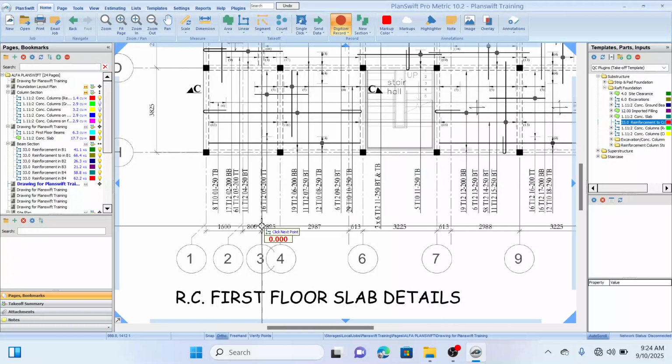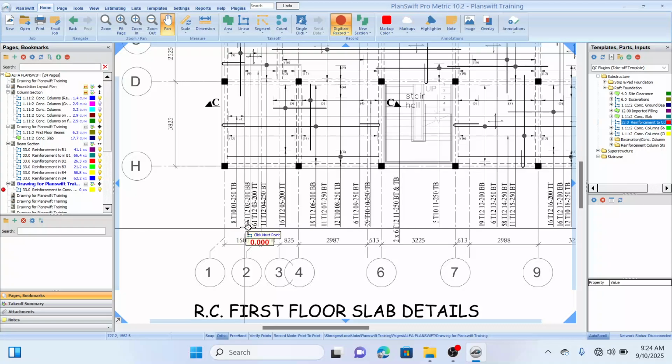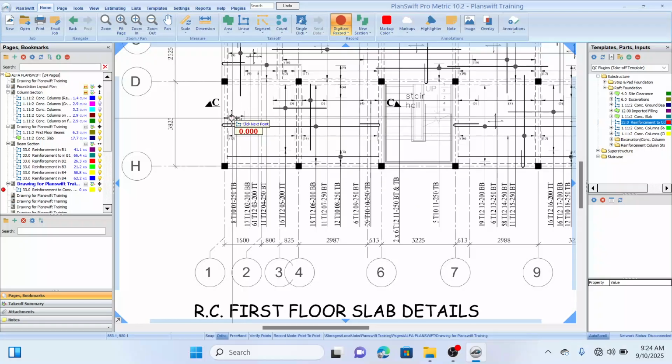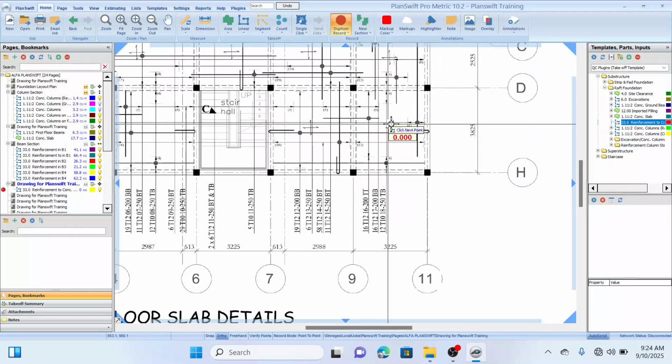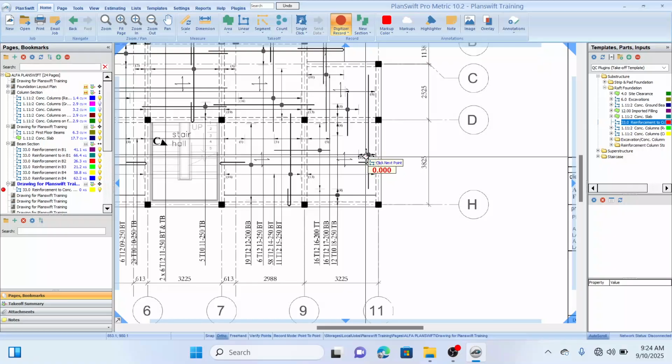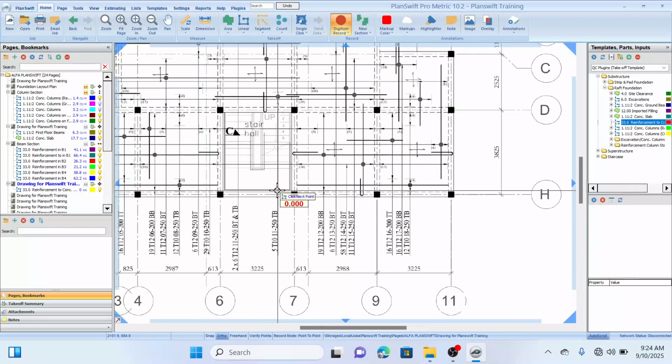So now the next thing is how to locate the reinforcement on the plan right from the description. To locate the reinforcement, just trace this down to the end of the arrow. Then when you get to the end of the arrow, you trace this down that way. So this is the reinforcement. We'll have this thick black dot. That's the location of the reinforcement. The reinforcement spans from this point down to this point. And see, let me trace it again.